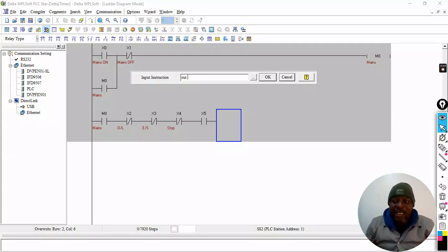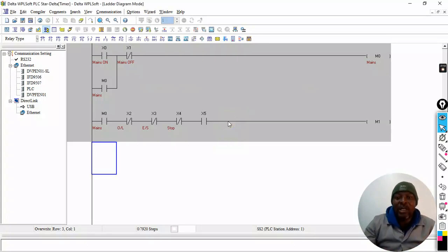So we're going to use again M1. Why? Because it's an internal relay. We are saving. I mean, if you know the cost of conductors, and depending on how big the conductor is, what is its current capacity? What size motors are we dealing with? It can be a very huge conductor, and it can be very expensive, and can add to expenses. So in this case the PLC eliminates not only the conductor, the timers are also expensive. These pneumatic timers are very, very expensive. So the cost can get explosive if you don't control your command.